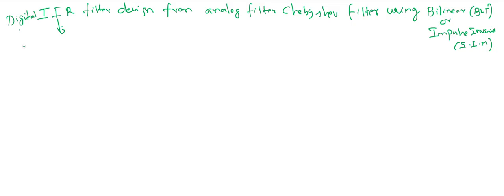Okay, so in this you can expect the question, compare what is FIR and IIR. So finite impulse response and infinite impulse response. There is a recursive, feedback, recursive filter. This is a non-recursive filter. That means there is a feedback in the system.